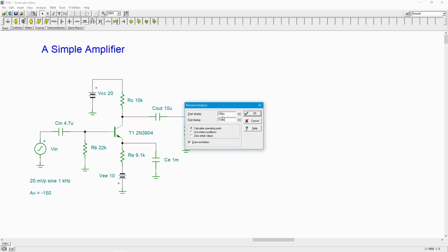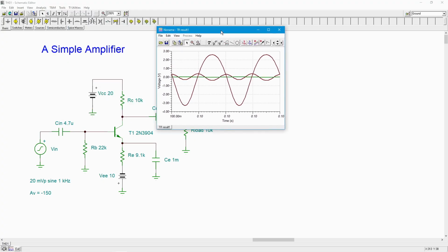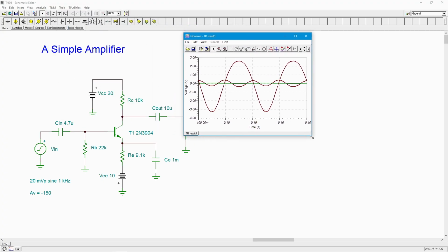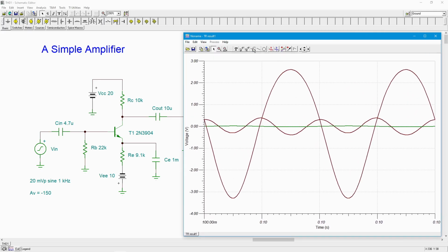So let's do a transient analysis and see what we get. I'm pushing this out a little bit because I want to make sure that everything settles for these caps. So I'm not starting it right at 0, going from 100 to 102 milliseconds. Let's bring this over here, open it up a little bit so you can see it better, and get a legend on here.